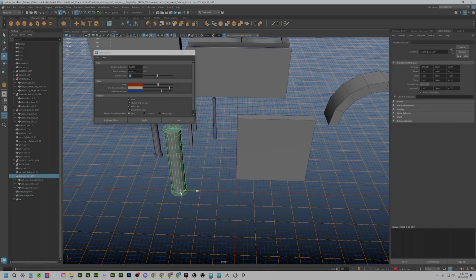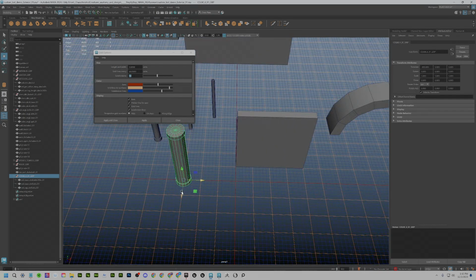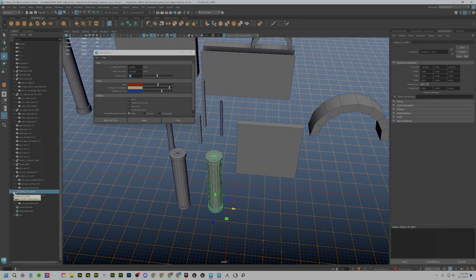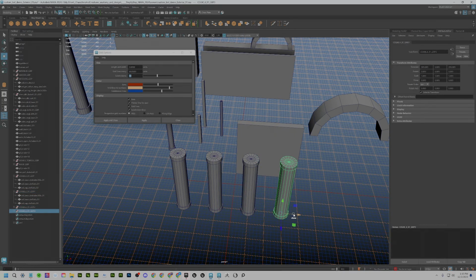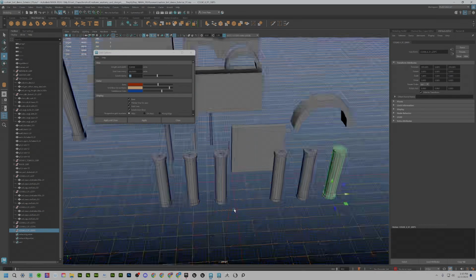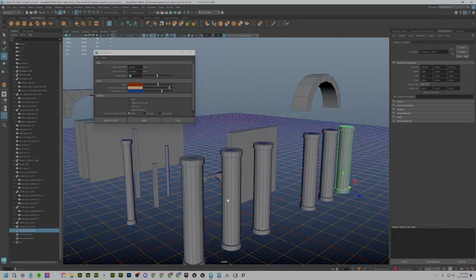Now if I have this done here, you can very easily take this group and we'll bring it over here. And if you wanted to do a little foyer in front, we can just do a shift drag, and it does the whole group, including all the pieces that are inside of it. So I'm just holding down shift, and if we go up arrow on that, it's going to go up to the group controller. So if I want to create a little opening here, just go up arrow, hold down shift, and drag it over.